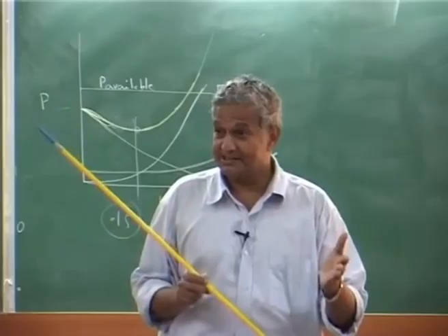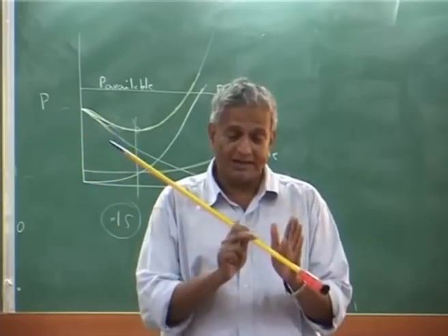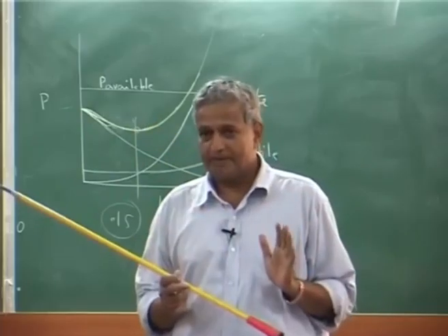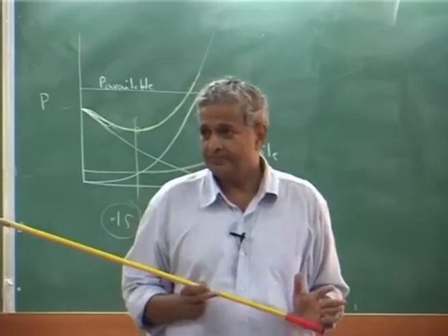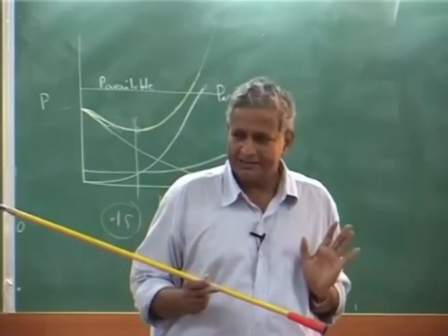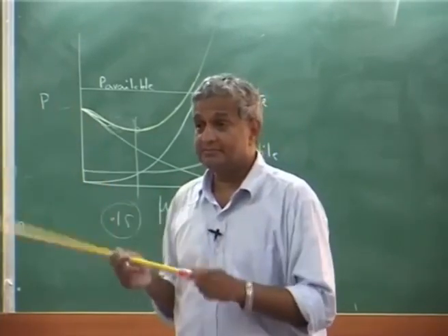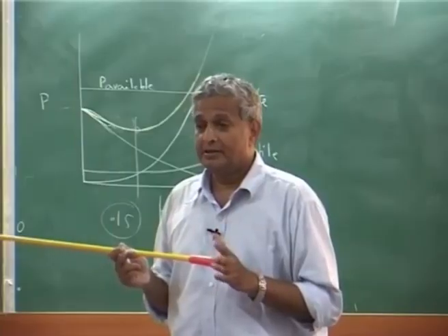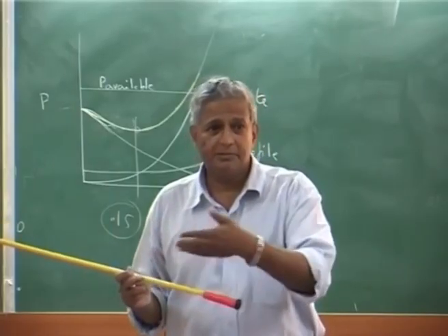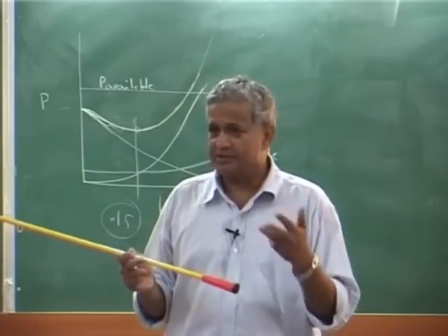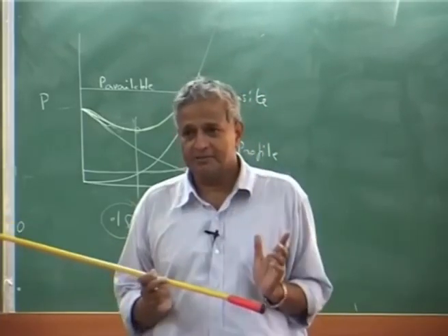because that is very essential, which means you study only the dynamics of the blade in forward flight. You do not bother about anything else, just how my blade will vibrate for a given pitch input. Given pitch input is the pilot gives theta naught, theta 1c, theta 1s.